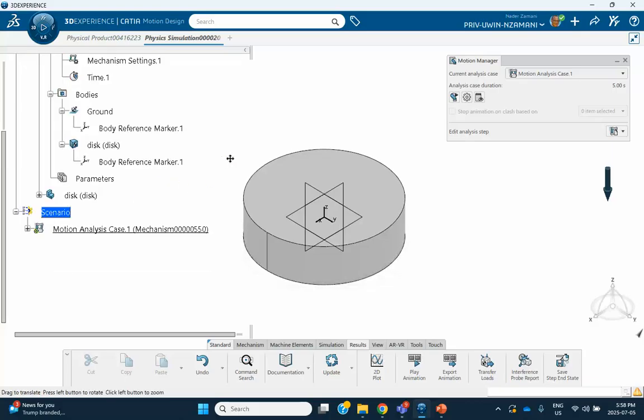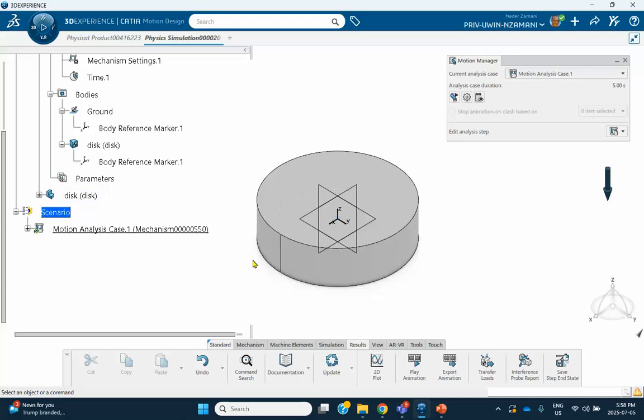So we're going to create all the joints ourselves. Now, what are the joints that we have? Well, first of all, we have to fix something. Even if I don't fix the ground, this ground is definitely fixed. So I'm not going to even bother fixing this ground. I'll leave it the way it is. So this is going to be automatic. You see that? There's an anchor there. So it's unnecessary to fix this thing.